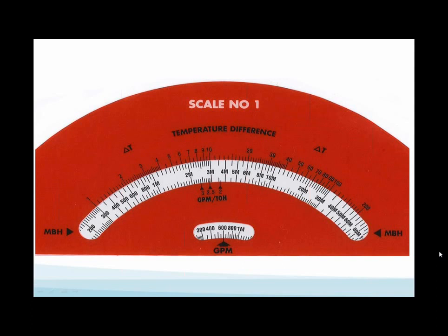And the M makes it another 1,000. So in reality, we got, what, 6 million BTUs when we see 6M. And that's the manual system sizer. And you see it gives you the answer of 6 million BTUs or 6,000 MBH.